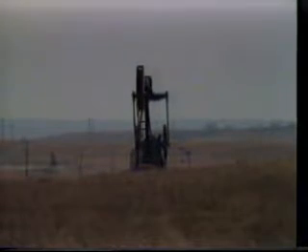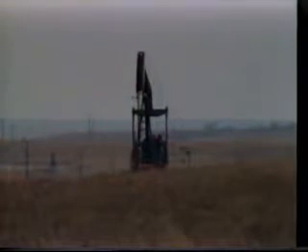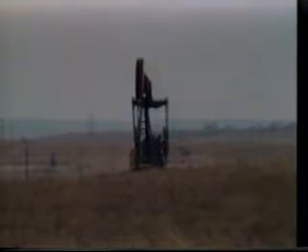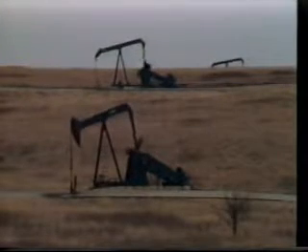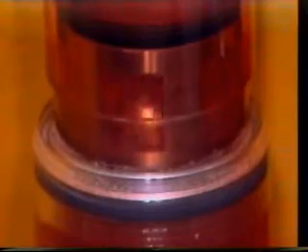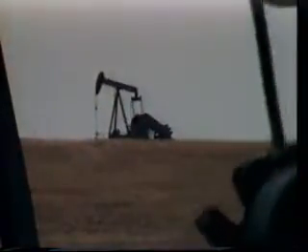Subsurface pumping can be achieved by various methods. The most common is sucker rod pumping, where the pumping motion is transmitted from the surface to the pump by means of a string of rods placed within the tubing. The subsurface pump is essentially a plunger and valve arrangement within a tube or barrel. When the close-fitting plunger is lifted within the barrel, it creates a low-pressure region below the plunger, which is filled by fluid from the formation, and simultaneously the plunger and rods lift fluid up the tubing.